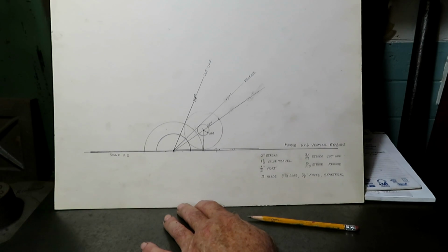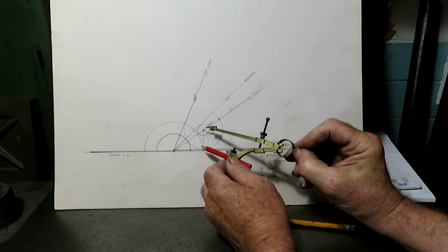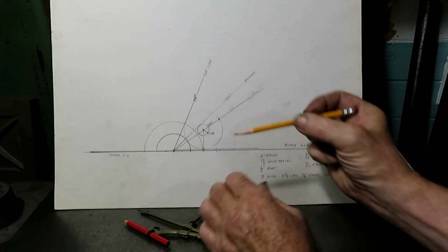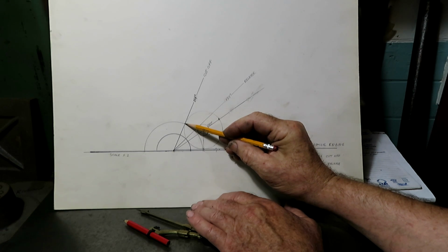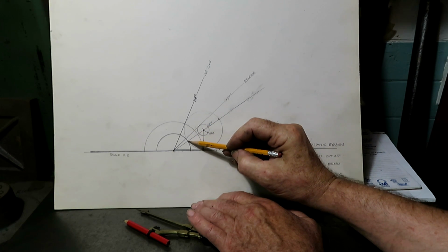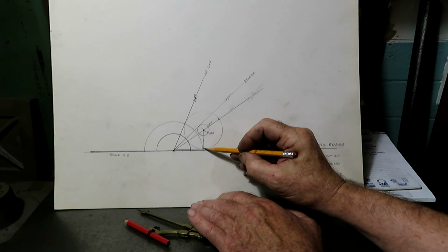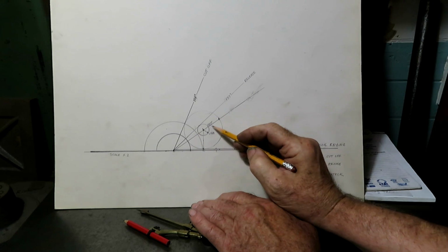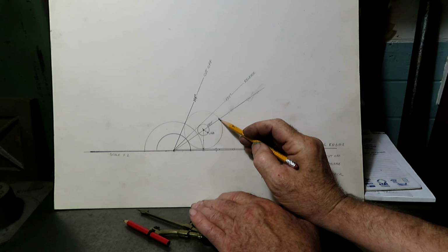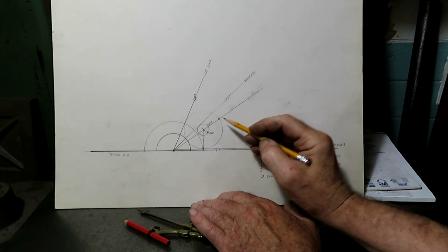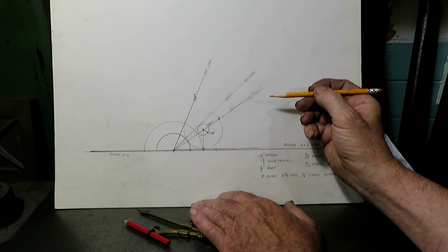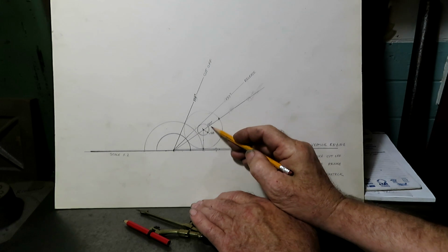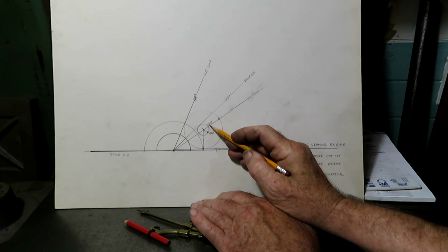And then you've got to fiddle around a little bit with your compass and find a point and a radius that will draw a circle tangent to three things: this cutoff line, this inside port line, and this lead line. And once you get that circle in there, the radius of it is actually the outside lap of the intake valve. That is the amount that it sticks up above the port on the top and the bottom. And on this, after I divided this distance here by 2, it came out to 0.582 inches.